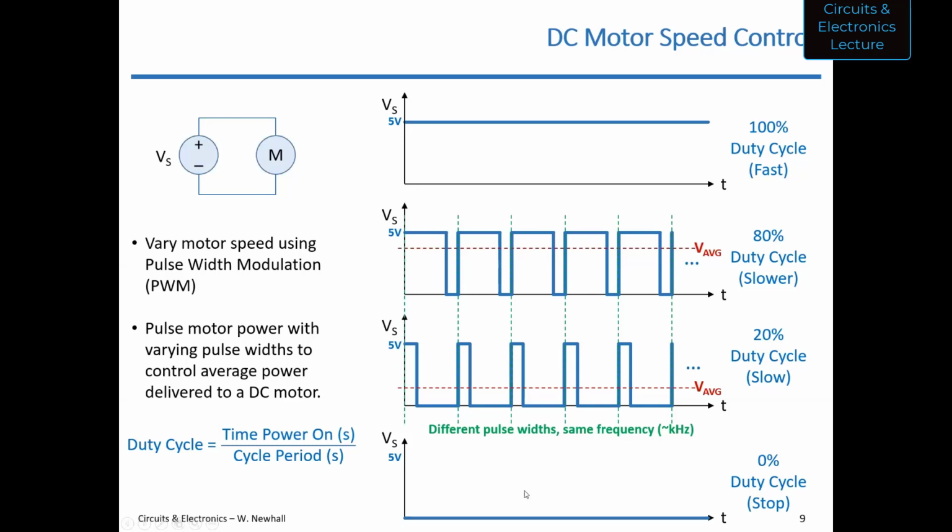Now, we talked about pulse width modulation. If there's an average voltage output, there needs to be some kind of low pass filter. In the case of the flashing LED, it was your eyes. Your eyes cannot react that fast. They have a low pass response to flashing light. So your eyes were doing the averaging.